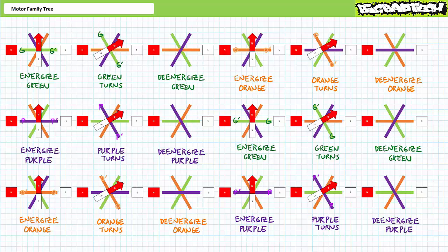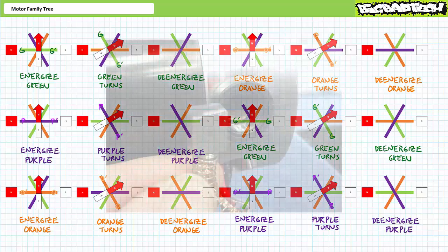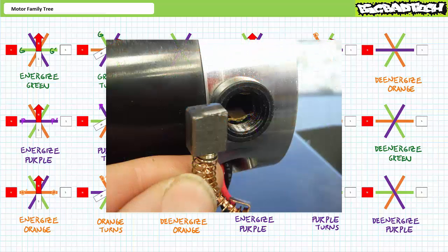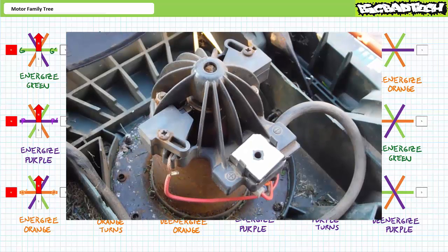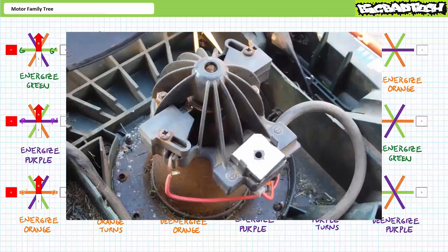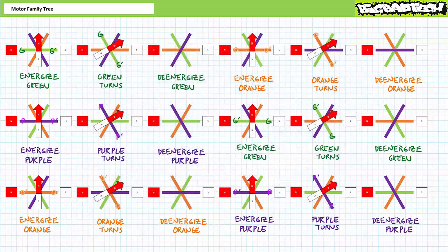More robust DC motors include more windings in the armature, such that the torque isn't pulsed or jerky. As with slip rings, the brush and the commutator itself are subject to mechanical wear or routine maintenance, and may necessitate periodic inspection and replacement. Additionally, since the commutator, unlike a slip ring, repeatedly makes and breaks connection, brushes may experience sparking due to inductively generated voltage spikes. For this reason, you may encounter DC motors with additional accessory windings, sometimes known as interpoles, to cancel out these effects.